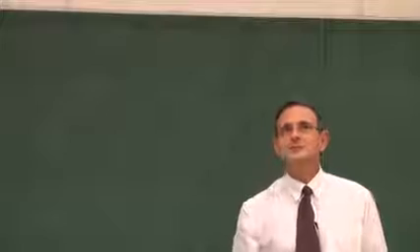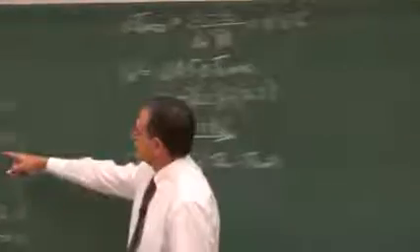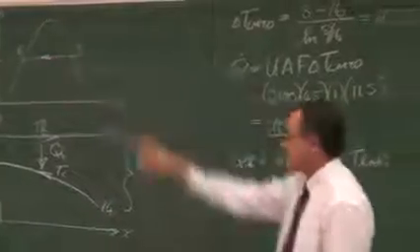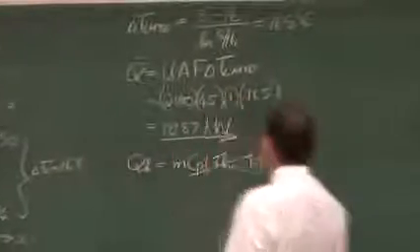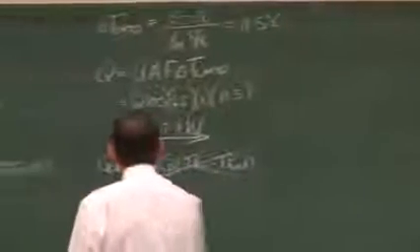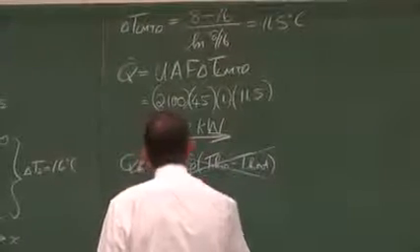Samantha, what's wrong? Yes, because it is in a two-phase flow region, the Cp doesn't exist. So we cannot use that. That is for a single-phase fluid. It is equal to the mass flow rate multiplied by hfg.